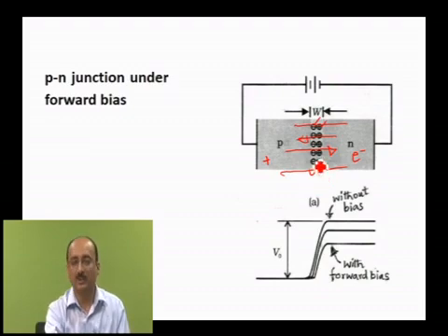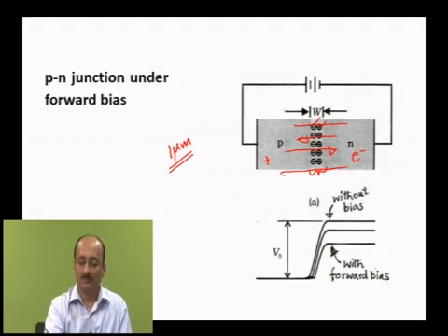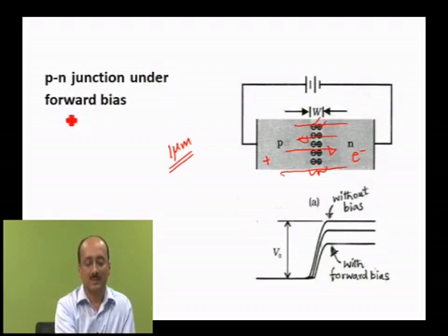So for depletion region to be developed, majority charge carrier diffusion is the process, and usually this depletion region width will be a micrometer thick, and biasing etc. will be done. Biasing generally means you are connecting a source of EMF across the PN junction. When you do so, depending on how you make connection, either the depletion region width decreases or it will increase. Now this is basically forward bias.